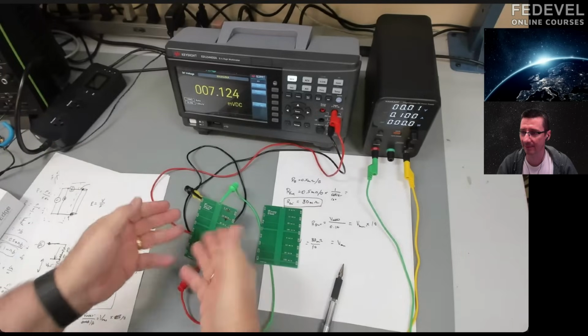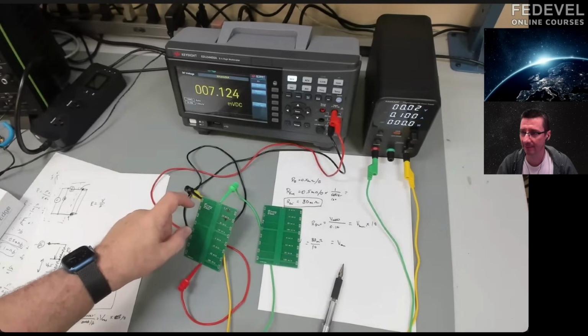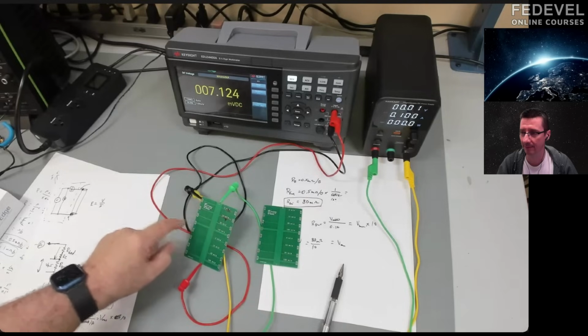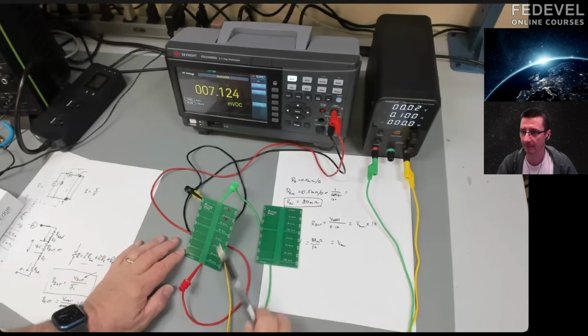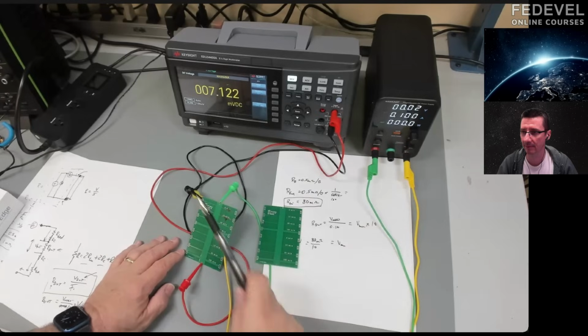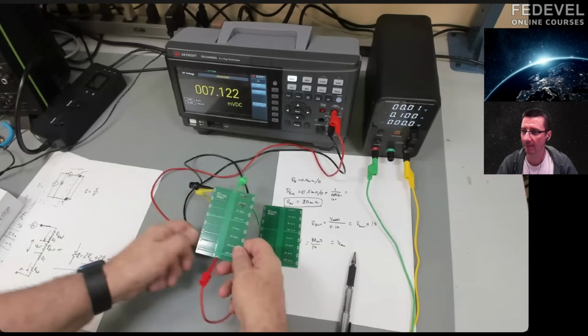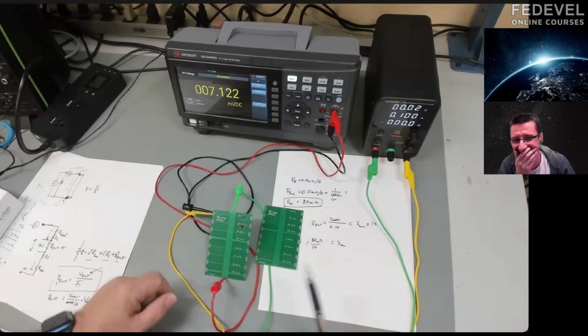You want to do it on a wide line because of the potential of etch back that you don't know about. The percent impact from etch back is much less on a wide line. But that means you're measuring really low resistance. That's where you want to use this technique of forcing a high current and separately measuring the voltage. Well, while I have this set up, let's blow a trace up. Let's ask that question.